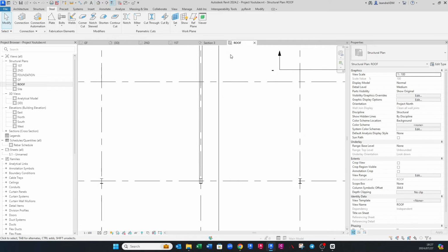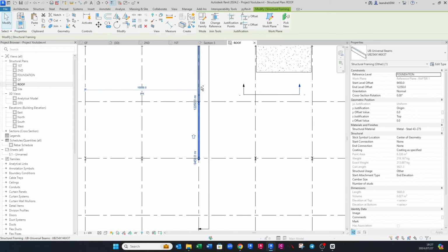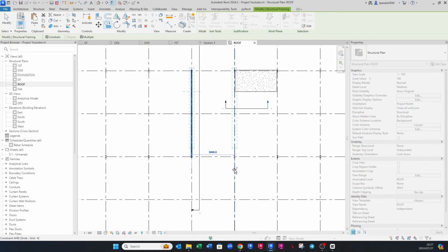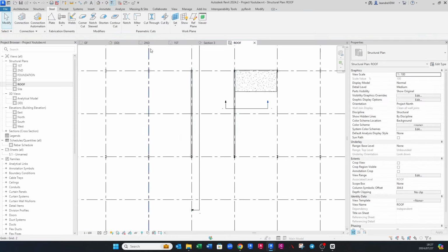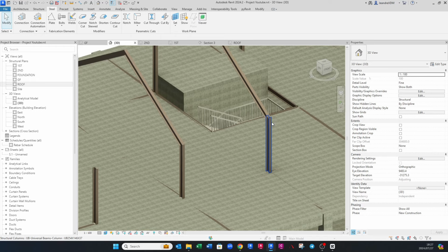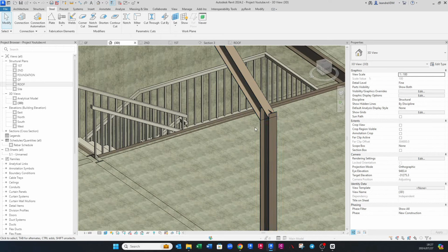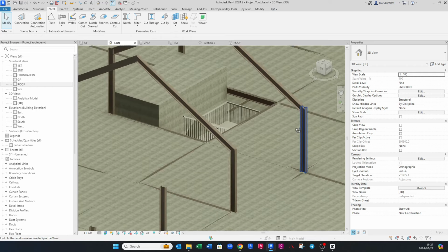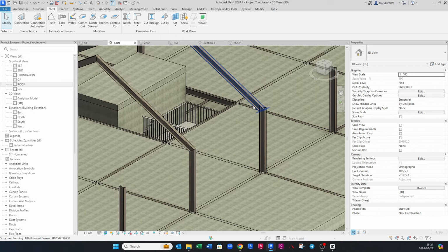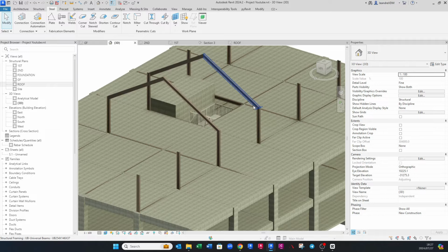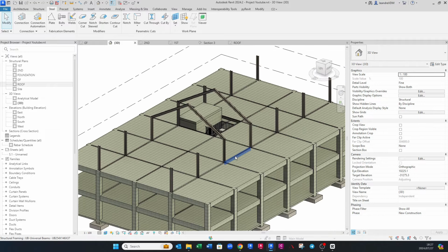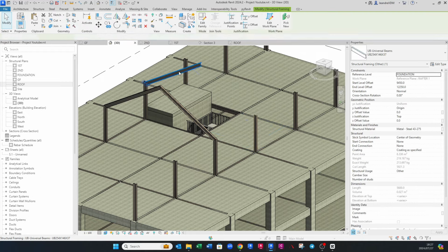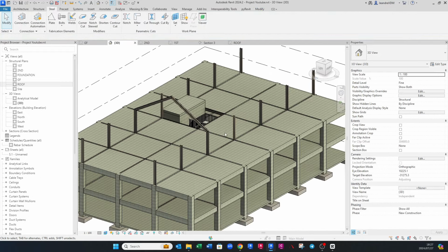Let's go to the roof layout. So if we copy this, only the rafters from grid line to grid line, I'm going to show you what's going to happen here. That miter is not going to form because we have not selected this element to miter with that element. So the easiest is actually to backtrack a bit and delete the elements that we've created.